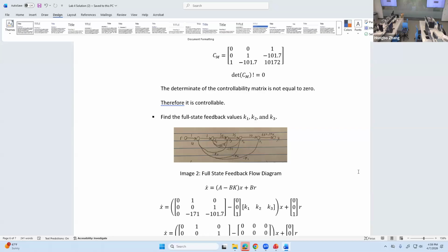That whole matrix is A. Right. Just following that x dot formula. Because then B is the 0, 0, 1. And then A is the matrix K1, K2, K3. You say the y part is not fed back, right? Only x is fed back. That's why I call it full state feedback. The y is not fed back.